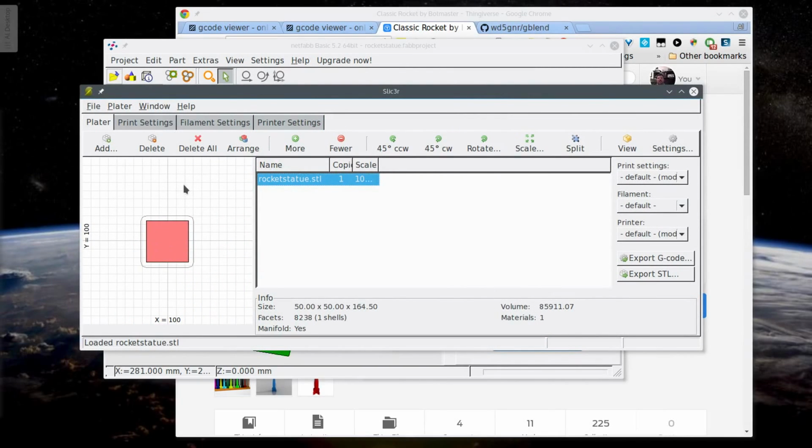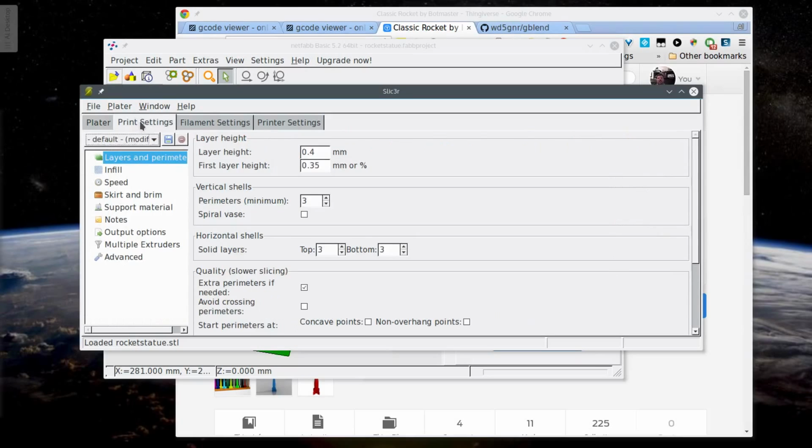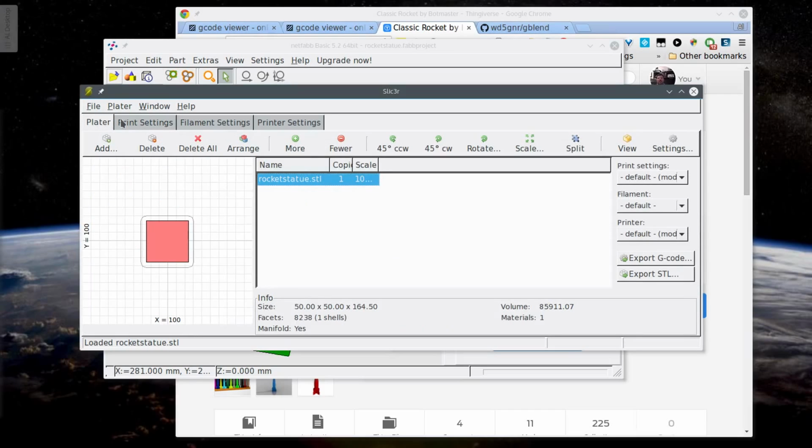So I've got a slicer here, and you'd probably have settings like a normal setting, and you could slice it once that way. Then you'd also come in here and make a setup with the spiral vase setting checked. That's going to set it to have one perimeter and hollow and do that kind of spiral type of hollow printing that we were talking about. And so I would slice it again and save that as a separate GCODE file. And I've already done that. I've got two GCODE files that I'll show you.